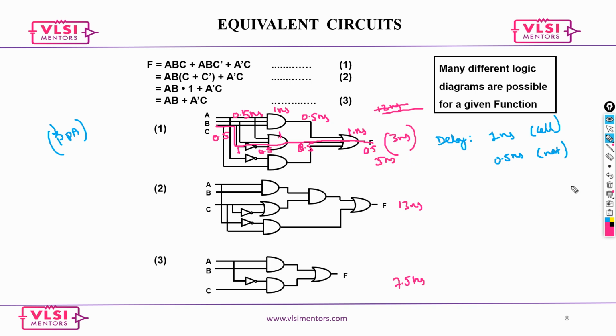So for the delay, you need to identify something called logic levels. That is what will give you more delay. So you need to identify the critical path, the one with more logic levels, and then calculate the delay based on that. Here the logic levels are 1, 2, 3 cells, and then you have 4 nets. That's the maximum, so 5 nanoseconds is the right answer, maximum.